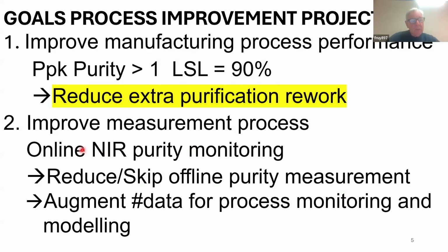Besides that, we will have to improve our measurement process, replacing that time-consuming chromatographic procedure by very quick online NIR purity monitoring. If this is possible, we can skip the offline purity measurement, and we can also augment the amount of data for process monitoring and modeling.